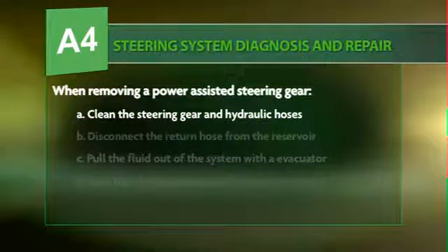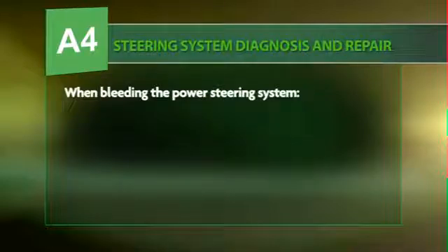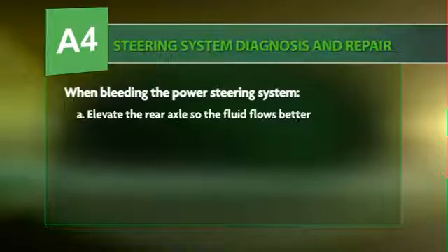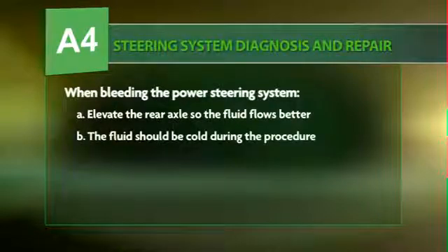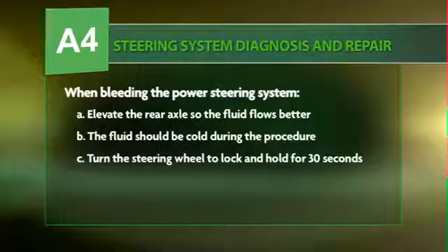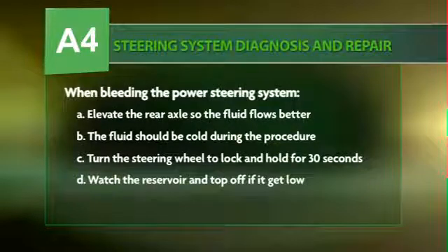Another question about power steering systems. When bleeding the power steering system, A, elevate the rear axle so the fluid flows better. B, the fluid should be cold during the procedure. C, turn the steering wheel lock to lock and hold for 30 seconds. Or D, watch the reservoir and top it off as it gets low. Well, part of the bleeding of the system is you're going to have the engine running, all right? So if you have the engine running, it's not going to be cold. So we can eliminate B as a possible correct answer.